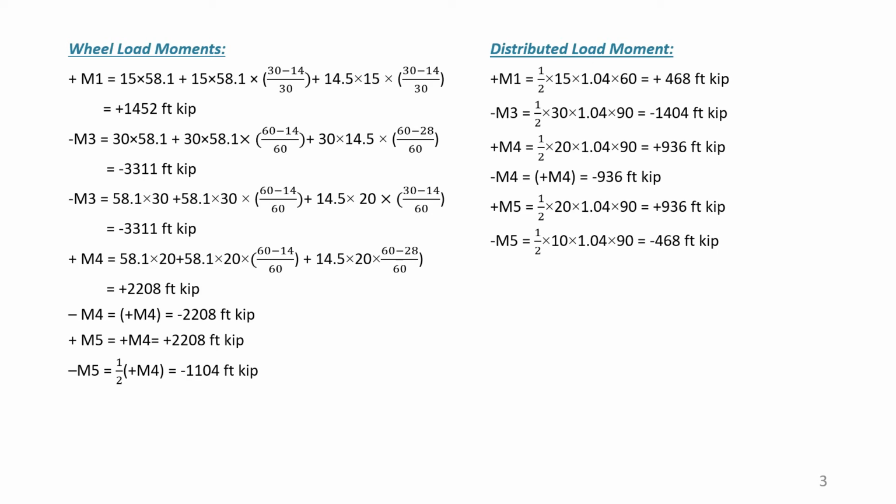We'll go to 0.4. Positive moment: you see that in the influence line triangle, the maximum ordinate is 20 kip feet per kip, because if we put a load at location 4, on the left hand side there will be a reaction of 1/3, and if we multiply this by 60, then the moment coefficient will be 20.